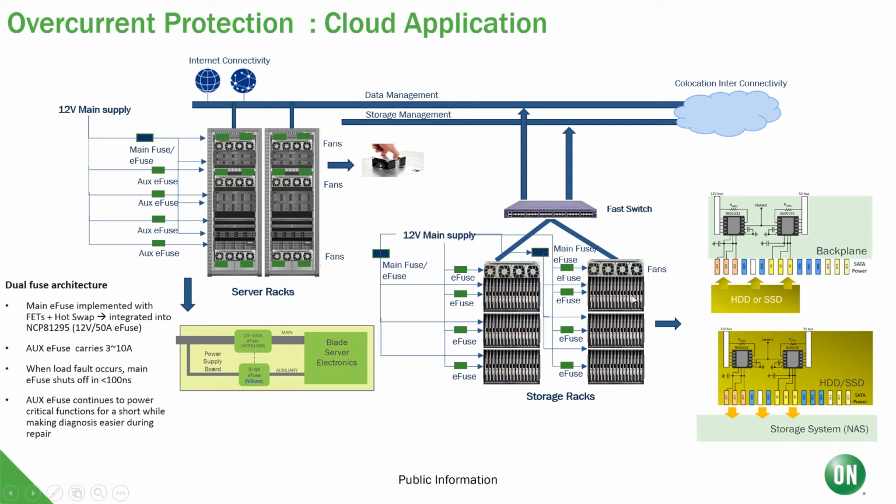Fans are also hot pluggable in server racks, as they will need replacing every so often, and you do not want to power down the whole system just to replace a fan. So naturally, it requires an eFuse as well.